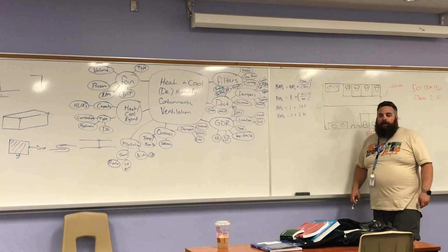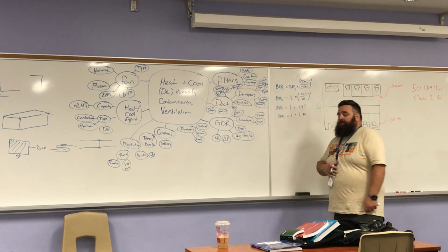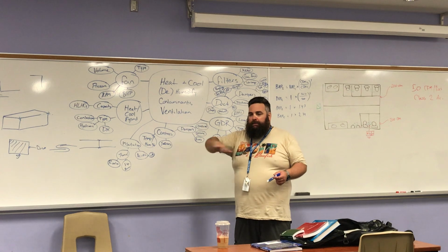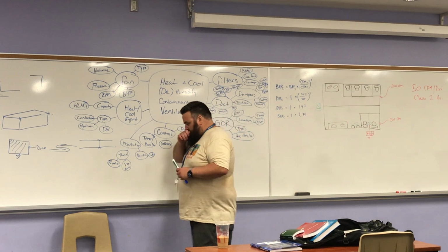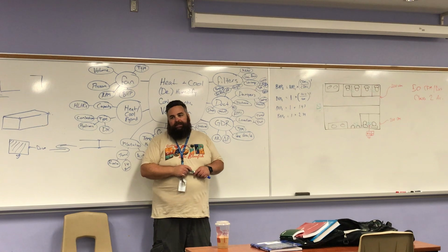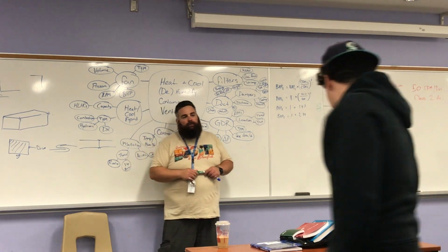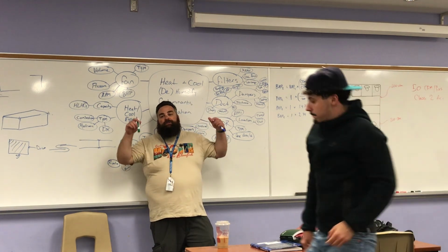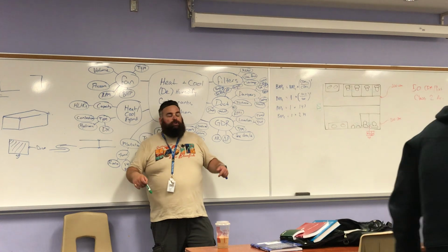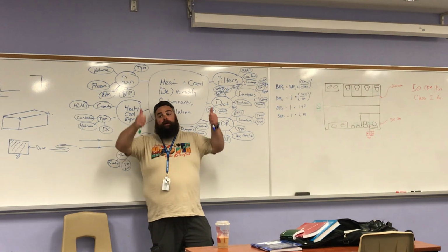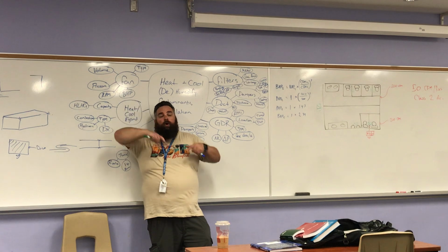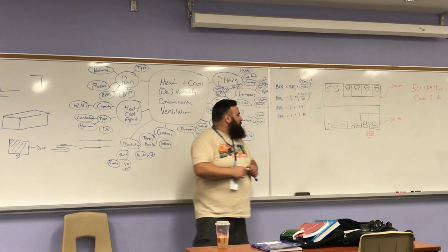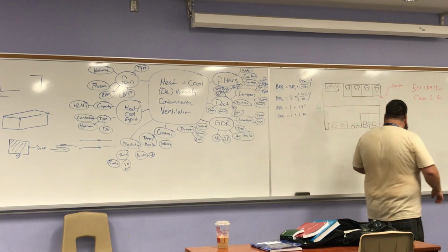One thing you also wanna be aware of, this is actually something I just learned recently, so that's why I'm sharing it. Remember I said about EPDM membranes on the roof, that white membrane? Animal fats and greases will eat away at that membrane, okay? So if you're exhausting commercial kitchen cooking equipment, you don't want that discharging right on the membrane. So you're not gonna spec a down discharge fan, you want it up a stack to carry it away, or you can get a special membrane that you put right around it that is resistant to that corrosion, okay? So I have a fan, how many CFM does that fan need to be?